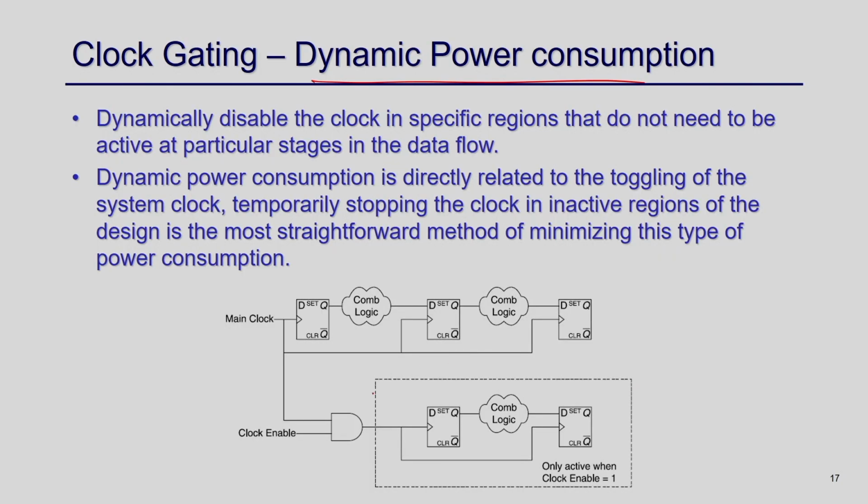Okay. Now, suppose you identify a part of the circuit, say this circuit is running forever, and I can know that from, say, cycle 11 to cycle 25, this circuit is not doing anything useful. The output it produces basically remains unused. But since the clock is coming, the input registers get modified every time you get new data. So there is a high chance that some signals toggle, and as a result this combinational logic gives a different output.